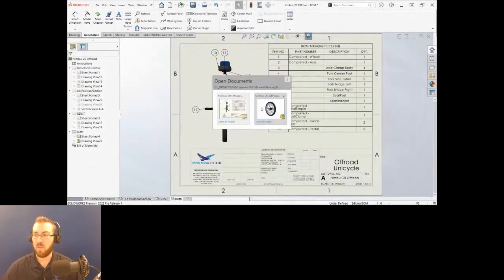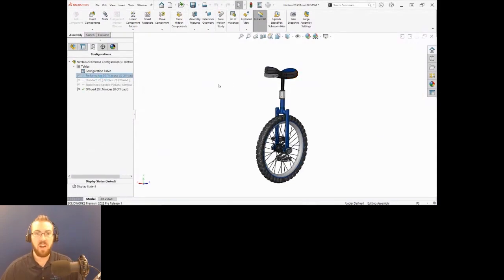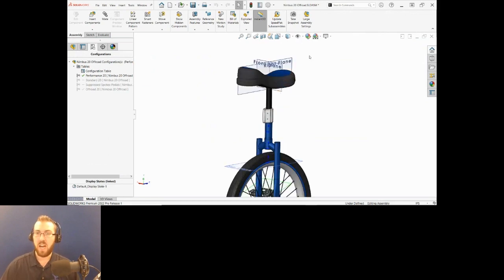So let me bring up another model here. I think everybody should still be able to see my screen. And if you have hide all types on, or even beyond that, if you for any reason have planes disabled, so if view planes is turned off and you try to use Q, it's not going to work. So those planes have to be on. If they're turned off, or if hide all types is turned on, that's usually the most common what happens. Hide all types will be enabled there when that little eyeball background is gray, and you try to use Q, you're not going to get anything.